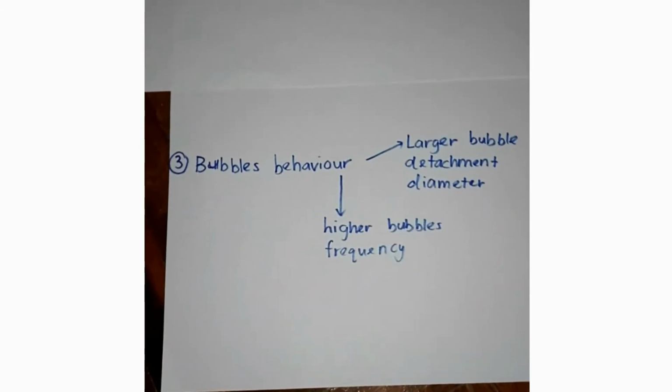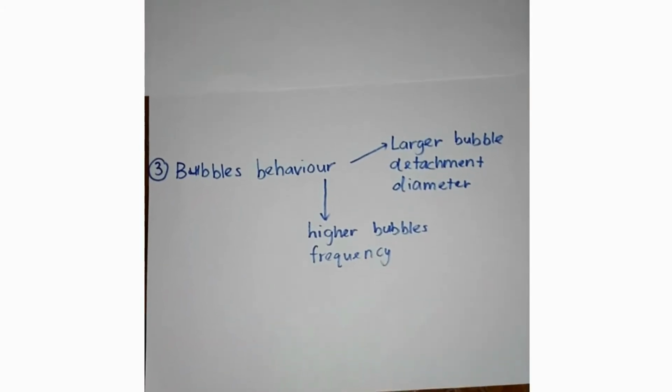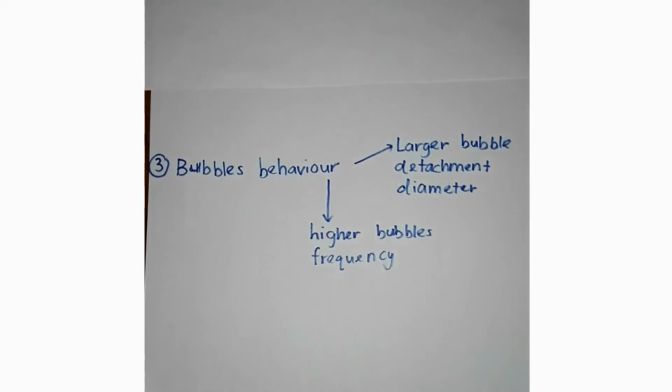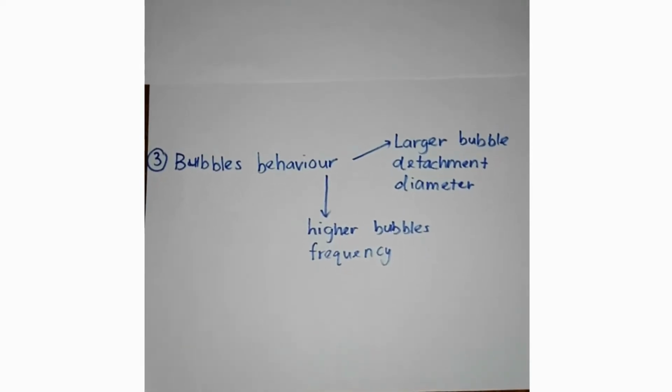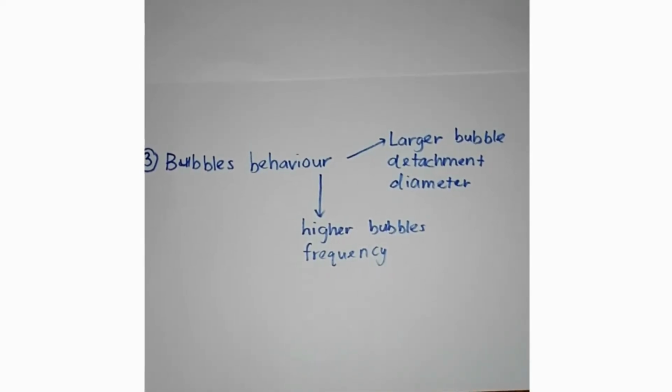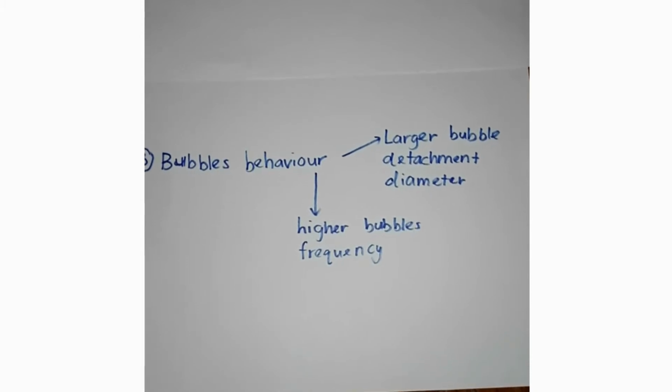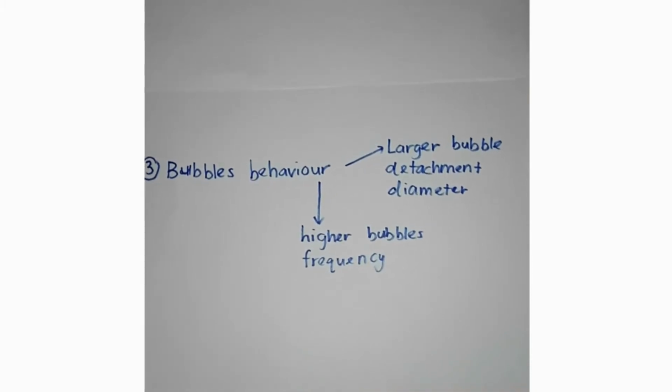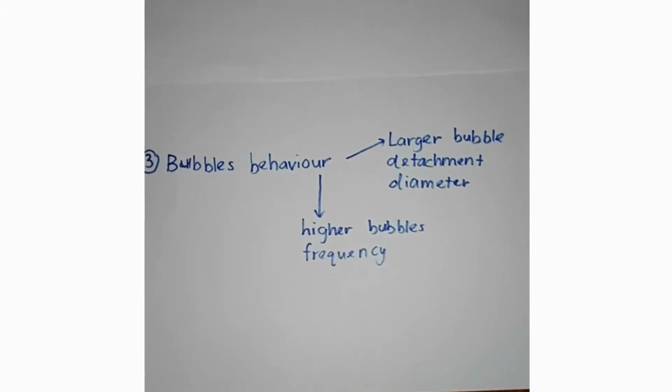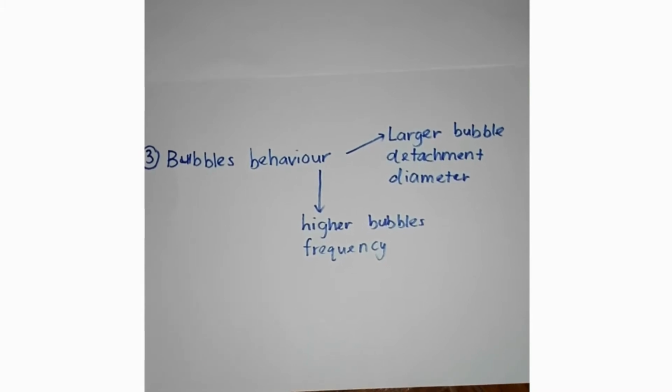And last but not least is the bubble behavior. With larger bubble detachment diameter and also higher bubble frequency, the heat transfer coefficient tends to increase. This is because the bubble behavior is dependent on the heat flux in nucleate boiling of the mixture.